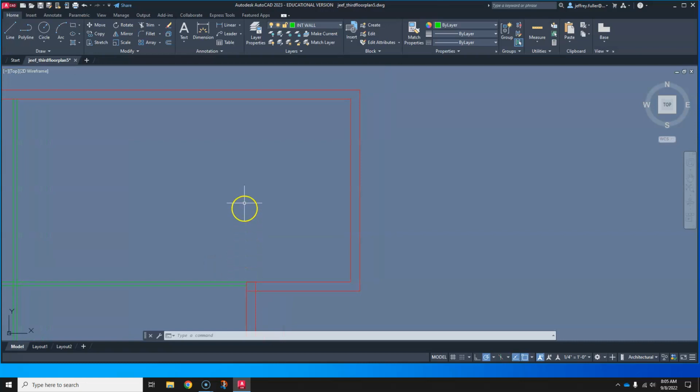The most natural thing would be to just draw a line right through here. You may want to come in just a little bit. So I think I'm going to do that. I'm going to click on the line tool. I'm going to turn on this reference point and then drag my cursor this way. And about right in here, put that wall, offset 4.5 inches, and offset it this way. Okay, so that,